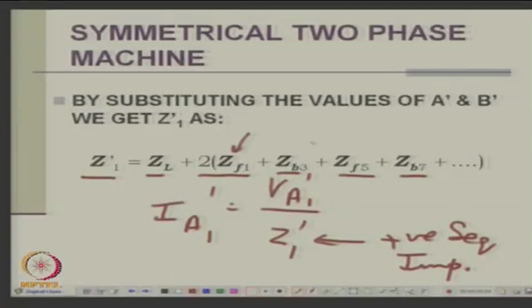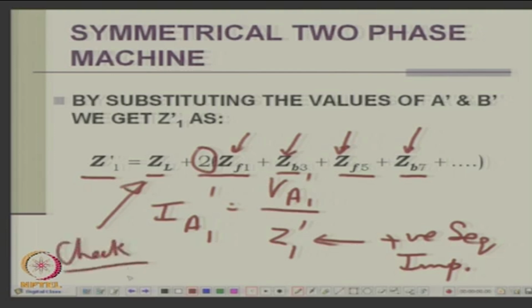So a positive sequence system in a 2 phase system will be associated with the fundamental, okay, plus third harmonic comes here, which was coming in zero sequence in a 3 phase system. Third harmonic backward only, that is backward rotating. Then you have a fifth harmonic forward, okay, then seventh harmonic backward, right. So it is totally different, and now it is a factor 2, earlier it was a factor 3. Okay. So you will have this arrangement. Now, I think you have to check these equations, so please check it and convince yourself how you get 2 and 3 and these factors, right.